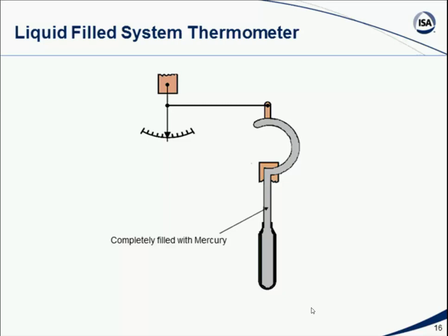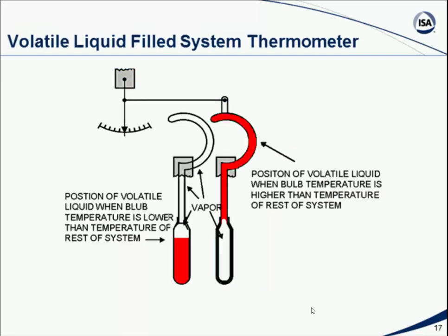And then, as I say, the C tube part up at the top, the Bourdon tube, will make small amounts of bending in and out based on the pressure change, and that can be used through mechanical couplings to indicate and move a pointer or some other device that can give us an electrical signal so that we can remotely send our temperature measurement somewhere else. So Bourdon tube measurements, and these were a very common measurement device for many years.